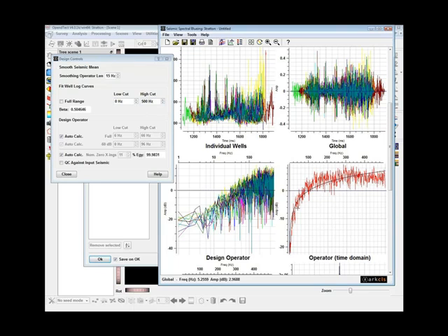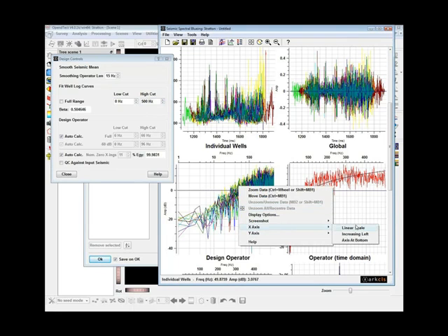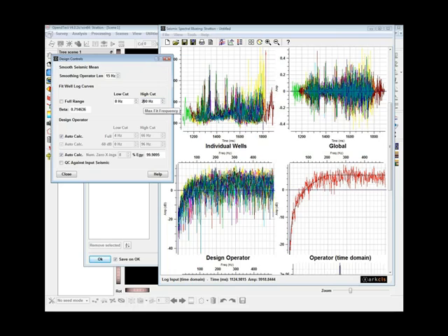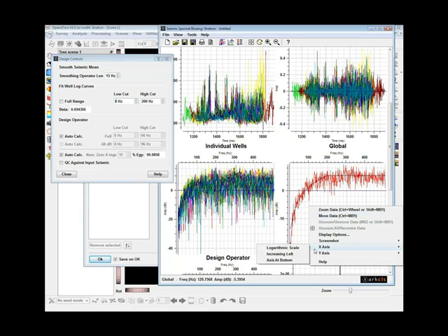If I change the scale to a linear scale for both charts displaying a spectrum, I can see that my data is becoming rather flat after a specific frequency, whereas the curve shows that it should be increasing with frequencies. Now, if I lower the high cut value, for instance, to 200 Hz, I can force the curve fit to become flat after this high cut frequency, which is here. For the low cut, I can also alter its value, and you can see that it will affect mainly the other end of the spectrum.